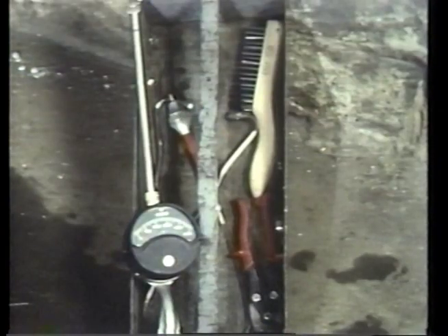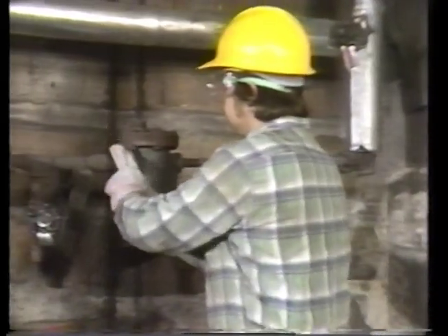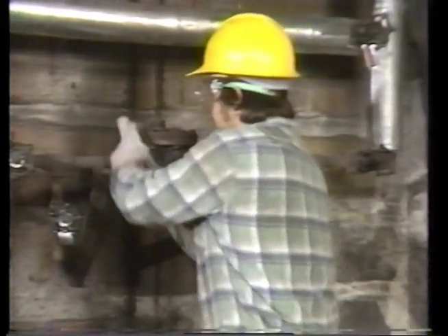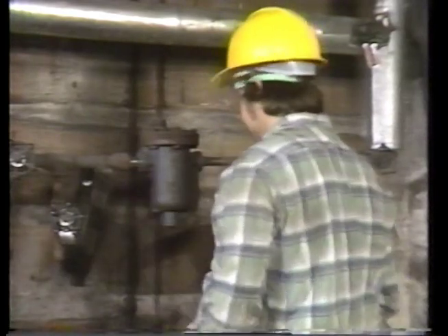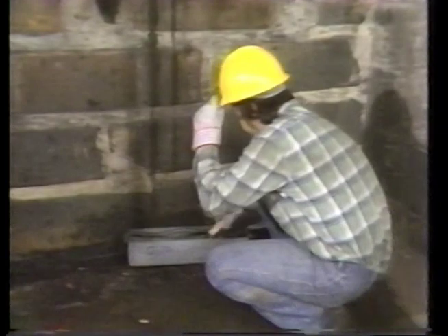So, if you know the steam pressures at the steam trap inlet and outlet, and you know the range of temperatures you can expect, the next step is to measure the temperature and see if you get the expected result. To do this, you'll need a pyrometer or similar temperature sensing device. Be sure to clean the areas where you'll place the pyrometer. You'll get good results with a wire brush or a file. Cleaning is necessary to ensure an accurate temperature reading.